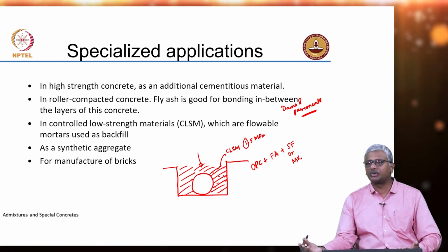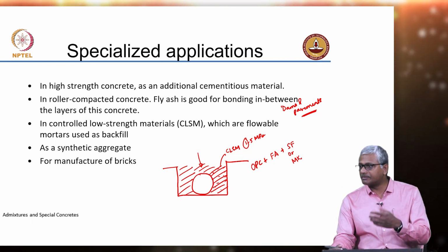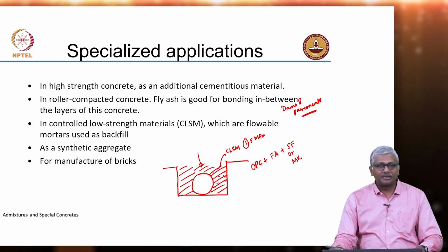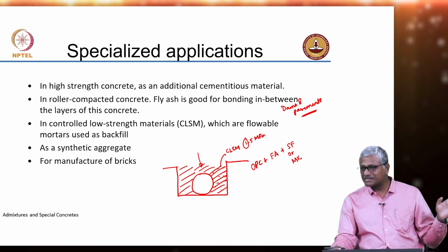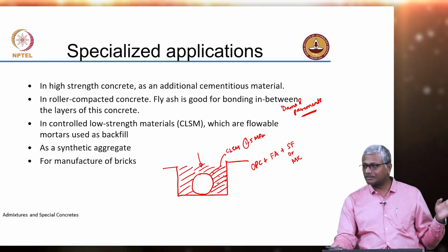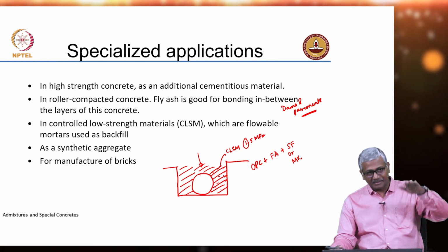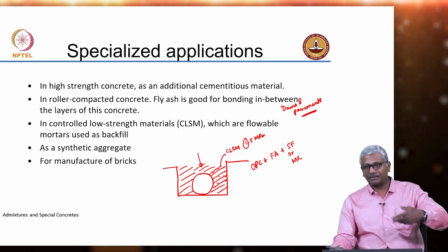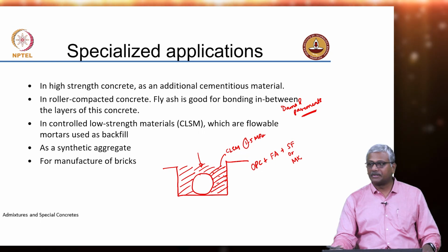Same thing when you dig trenches for your electric cables and so on. Our city municipalities have a habitual digging habit, no? Every time they start digging, and in many places the dug holes have not yet been completely closed. So, when they do it with soil, you know that there is an immediate subsidence, and driving over such roads becomes a nightmare for many people. In such instances, CLSM is a very good material.